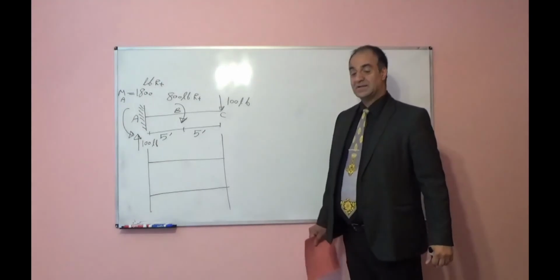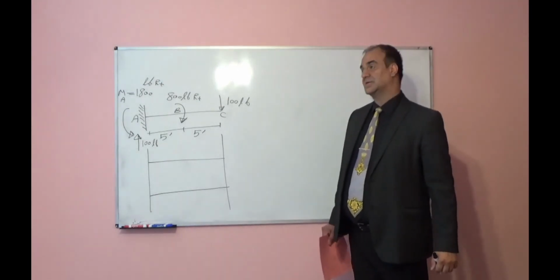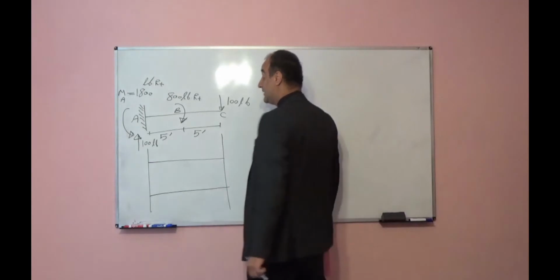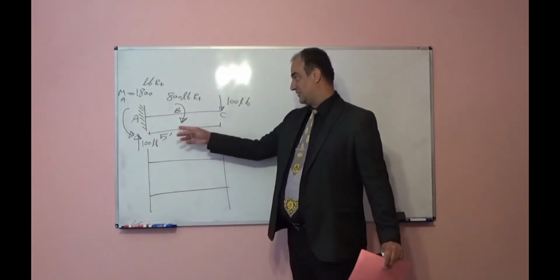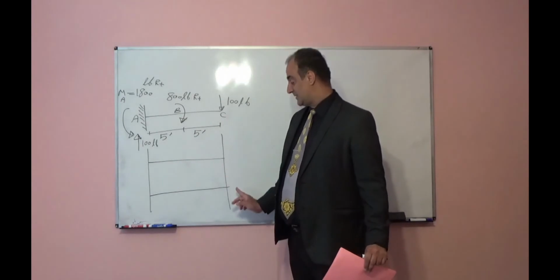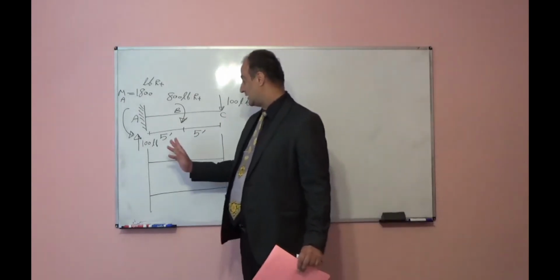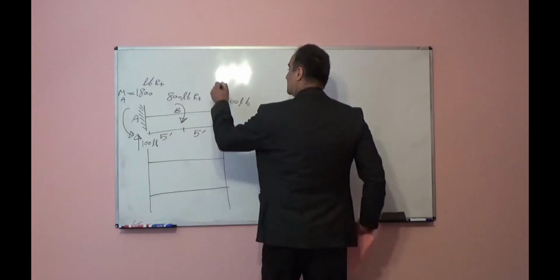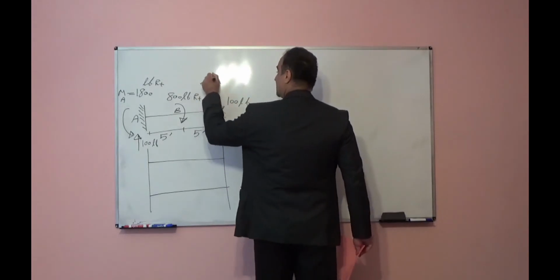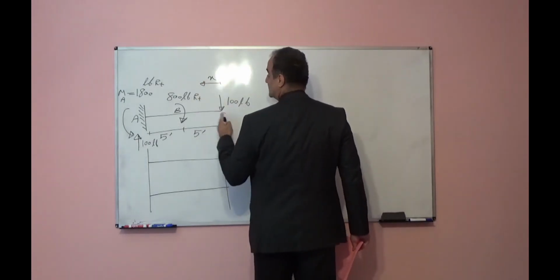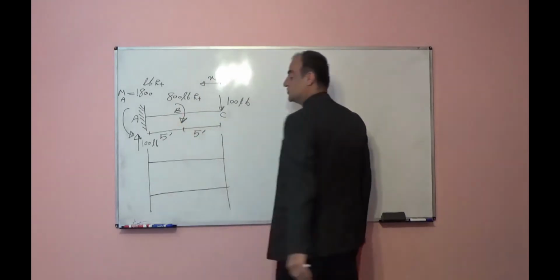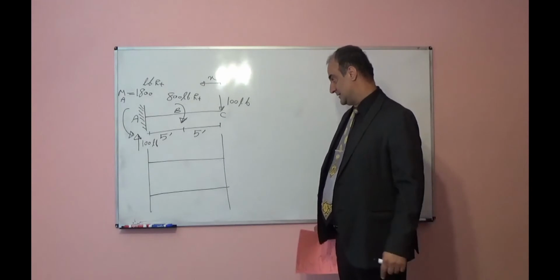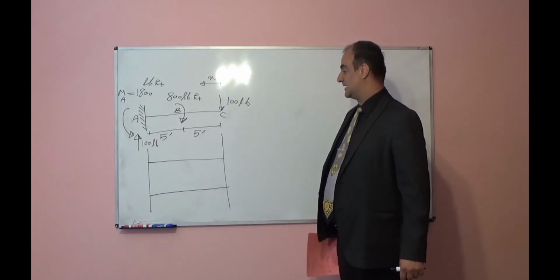Now, you can draw free body diagram, and you will need two free body diagram in order to represent the behavior and draw for shear diagram and bending moment diagram. One cut should be, for example, if you assume X from this side, one cut it should be between C and B, another cut should be between B and A. So at least two cuts you will need. But without of that, I can draw with two.